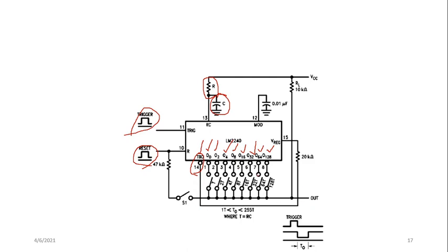Here 8 switches are shown, and 8 switches are given to the output. If I connect one switch, then I get that time period at the output. So if I connect the switch for pin number 8, I get 128T on and 127T off, so it will be a total of 255T. And then this T0 can be 1T to 255T.